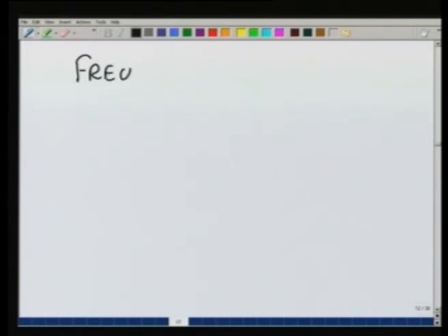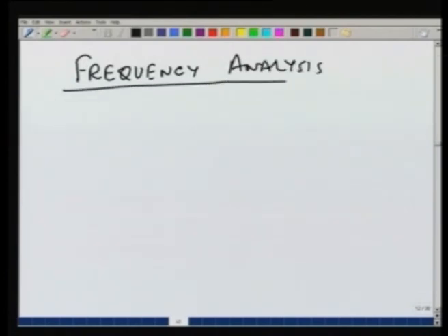The other analysis which we can do from the rainfall data is based on statistics and is called frequency analysis. So, not only are we interested in finding out how much rainfall occurs and what the maximum value is, but we should also be able to tell that within, let us say, a period of 10 years or 50 years or 100 years, what is the maximum value of rain which we can expect. Based on the importance of the project we can choose what is known as the return period.